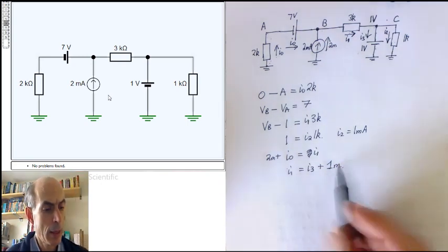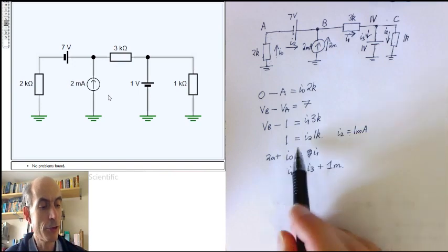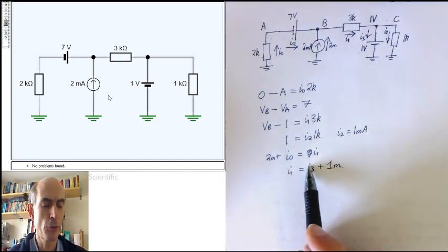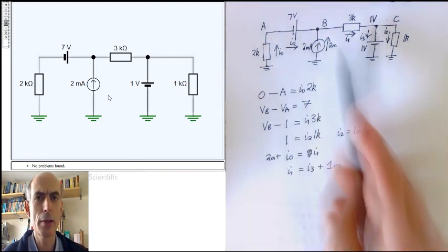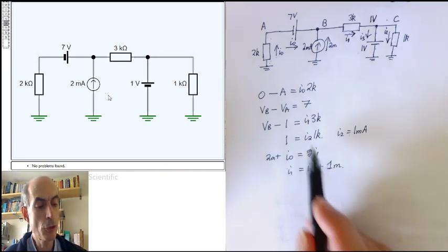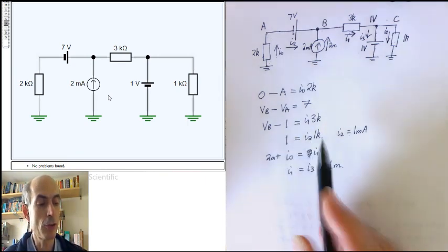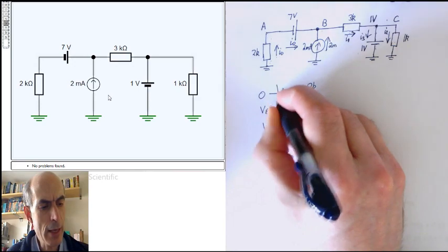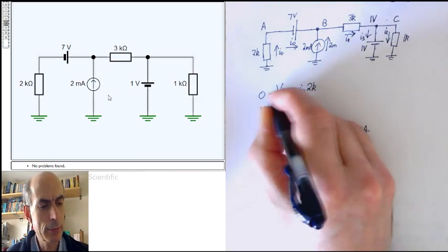Now, I2 only appears in this equation. We've got 6 equations here in 6 unknowns, which is rather better than the 9 equations in 9 unknowns that we could have had. I2 only appears in this equation, so we don't need to consider that equation anymore. Looking at where, that shouldn't be A, that should be VA, the voltage at A. Sorry.